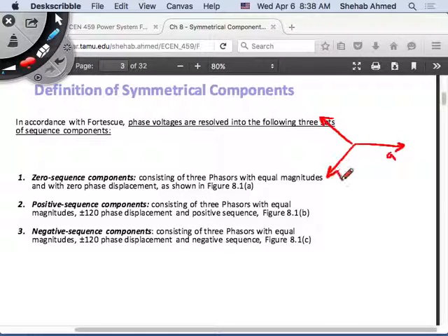If this is VA, VB, VC, my phase voltages or currents, this is I or V, it does not matter. These look balanced. They're 120 degrees apart, and they look equal. What did we call those previously? We sort of gave them a name. I said that if I stand here and these rotate and I see A, then B, then C, we gave this a name. What did we call those? Positive sequence. We call those positive sequence.